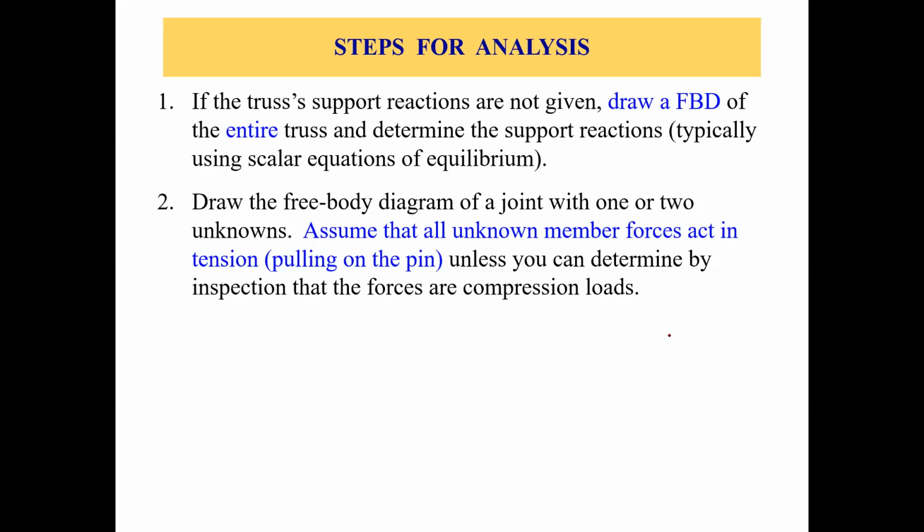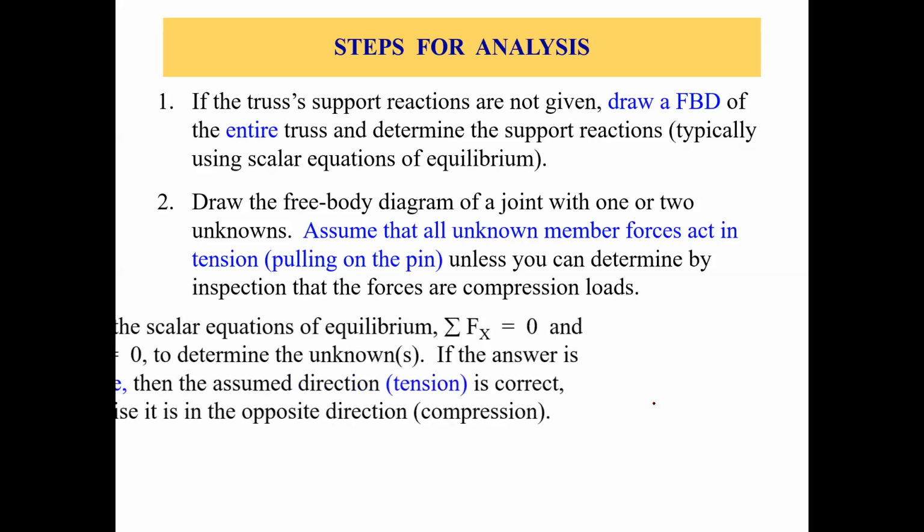Okay, so assume that all unknown member forces act in tension, unless you can determine by inspection or visualization that the forces are compression loads. We already talked about it in the last slide. So make sure that you take tension in all the forces, unless you can make out that this is a compression force. Then you can make it a compression force. Otherwise, take tension in all the member forces.